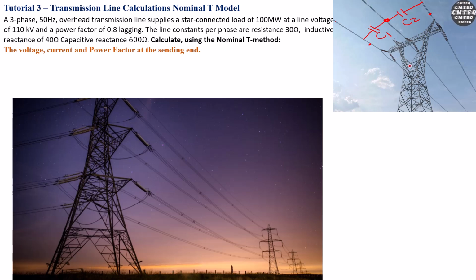Well, when you look at this transmission line pylon here with 3 wires, basically 3 conductors, line 1, line 2, line 3, we've got a representation of C1, C2, which are the capacitance of the line. Now, the capacitance in the transmission line is inherent to its physical construction, okay? It naturally exists between the conductors and the ground, due to the separation, like the distance between this line and this line, and the physical properties of the insulation and so forth. Now, in reality, this capacitance is distributed continuously along the length of the line.